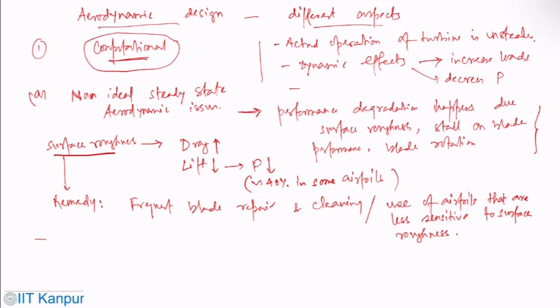Obviously, the stalled airfoil would not exhibit a simple relationship between the angle of attack and the aerodynamic forces, which is evident from the lift and drag coefficient data. On top of that, you can have turbulent separated flow conditions, which can occur during stall and can also induce rapidly fluctuating flow conditions.